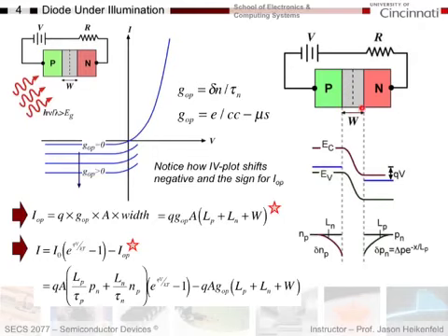But notice the width also includes my diffusion lengths, LP and LN. So it's basically the cross-sectional area, the width of the depletion region, and within a diffusion length of the depletion region as well, which is, we said, any of the carriers generated within LN or LP or within W will be swept across by the E field. And so that's how I calculate my total width of the optically generated area that contributes to optical current.